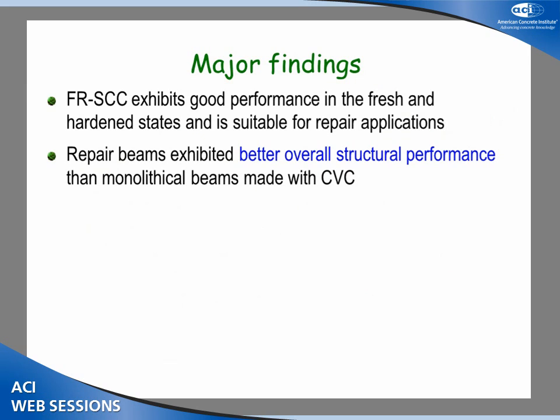And the findings are, out of what I presented, is that we feel that the fiber-reinforced SCC is exhibiting good performance, both in the fresh concrete stage and the hardened concrete stage, and is suitable for repair applications to reduce crack widths and improve durability, and especially reduce the restraint shrinkage that we also tested that I did not show.